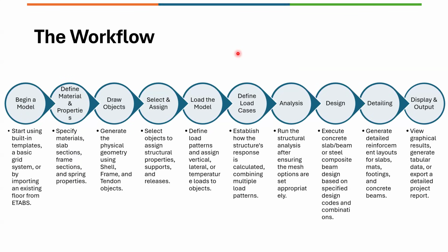You have a plugin that sits with the BIM program, the Revit program, and you can transfer the model to SAFE. That is also possible with ETABS as well. So the same import option is available here in the SAFE program. Other than that, you also have DXF to import geometries easily. I'll try to show a few examples.